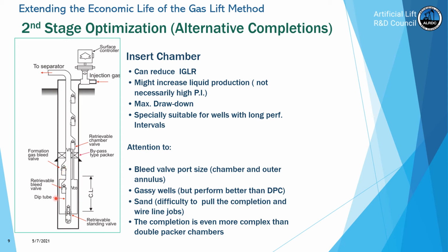But that combination acts as a separator, as a huge separator, because gas will try to go up and the liquids will go down. So you should be able to handle gas in a better way. But the operation of this type of completion is exactly the same. And yes, you can always reduce the injection gas liquid ratio.